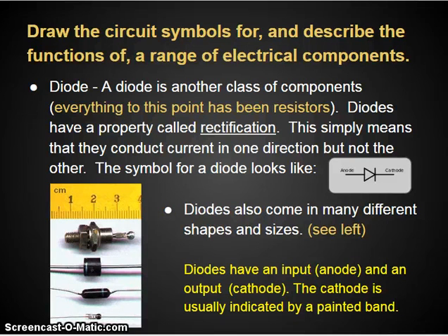Well, you can flip them around, and in some cases with LEDs, you can do something called multiplexing, where you can use a combination of resistors and LEDs and flip them back and forth and have them wired in a weird way, where you can use a limited number of output signals to control a large number of LEDs.